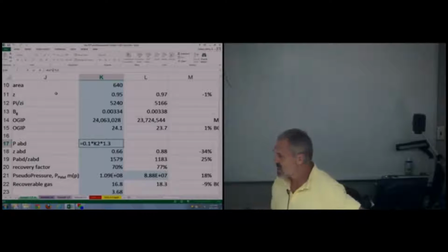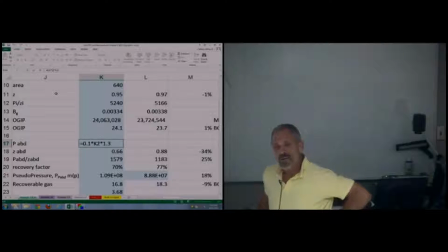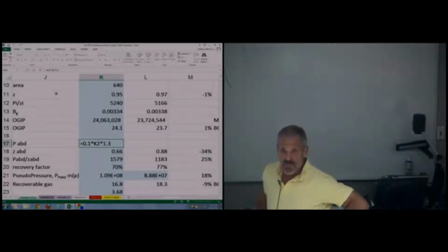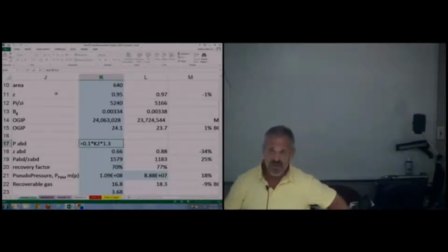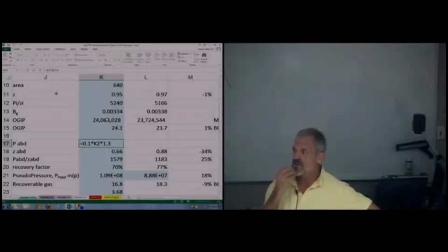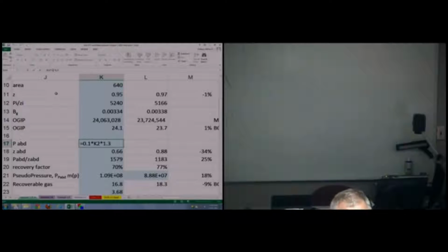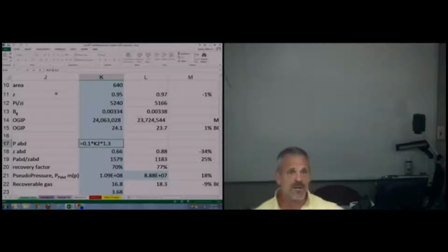If you use 145 degrees instead of 150 degrees as your estimate of bottom hole temperature, then you'll maybe have a 3% error. And I'll tell you why you're always going to be a little low on your reservoir temperature. Typically an engineer will get their formation temperature from what? What's lowered in the hole on every well that measures temperature? Downhole gauges? No, we do that occasionally, but I'm talking about every well, required by the state.